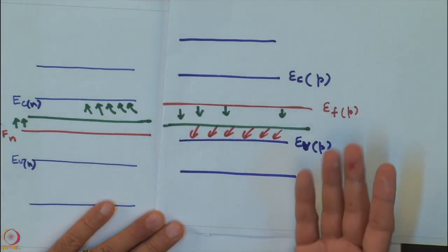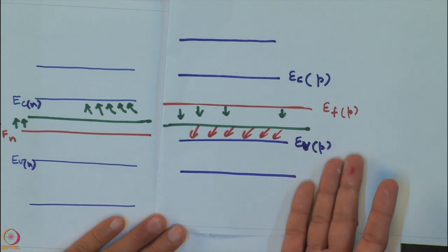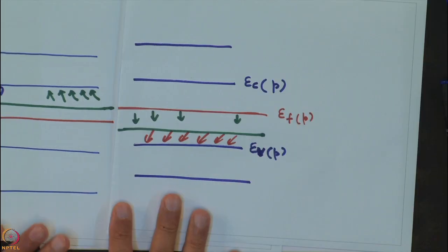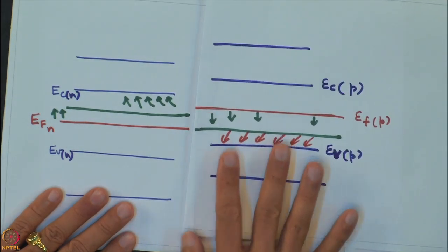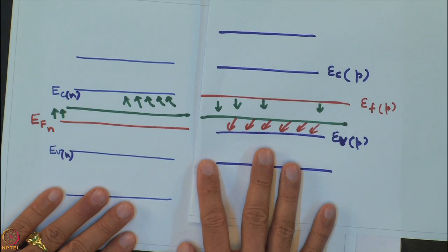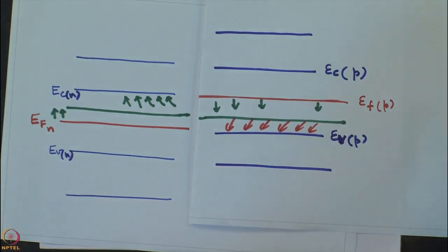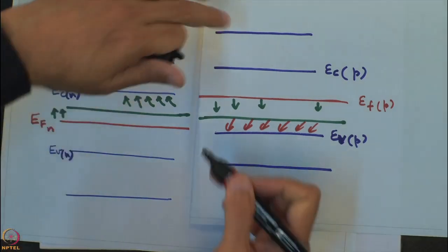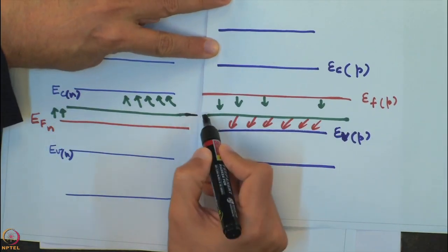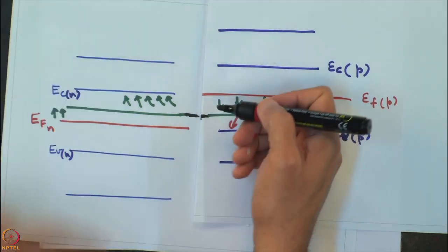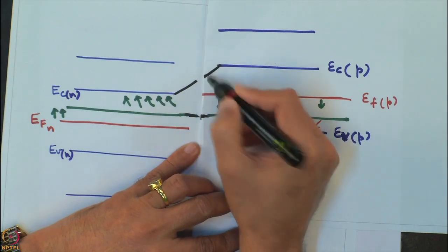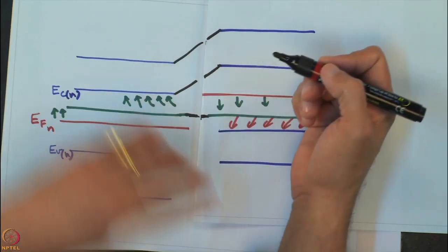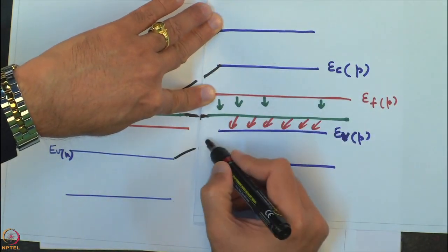The conduction band level and the valence band level on the p side actually shift and come onto this side, and I am just trying to show you this. So, what you see here is how things will be. I can combine my green lines on the two sides, which means that the Fermi energy levels are the same, while the other levels will all shift upwards. As you can see, I will have to make this kind of a structure over there.